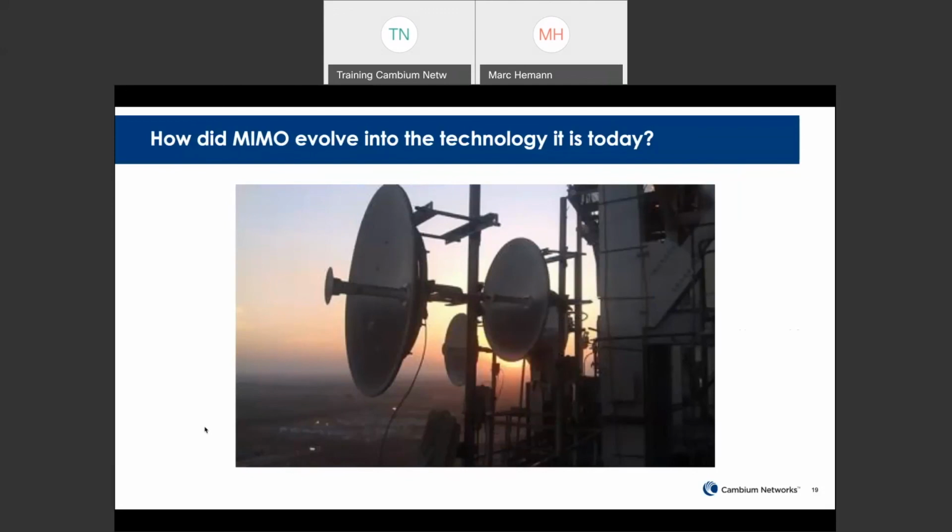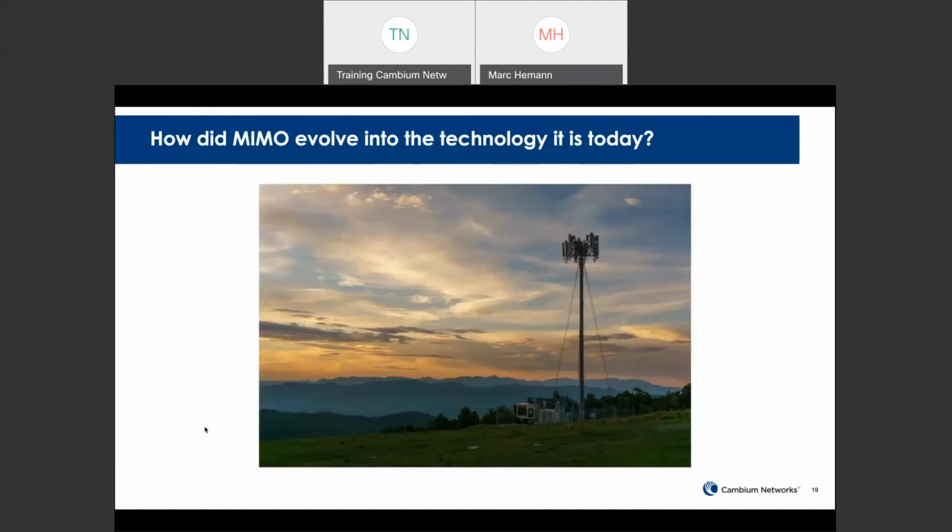The initial work on MIMO systems focused on basic spatial diversity. Here, the MIMO system was used to limit the negative effects caused by multipath propagation. This was only the first step, as the system then started to utilize the multipath propagation to its advantage, resulting in a stronger signal strength and reduced signal-to-noise ratios. Another benefit is that by splitting the data stream and sending each part through a different antenna, this allowed the throughput to be doubled, tripled, or even quadrupled.